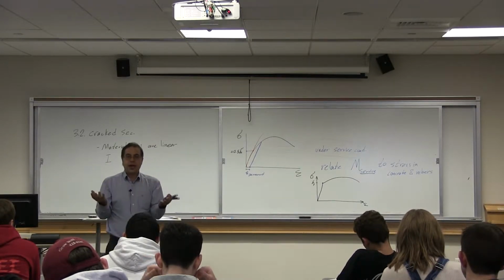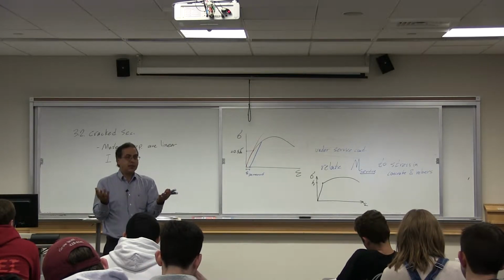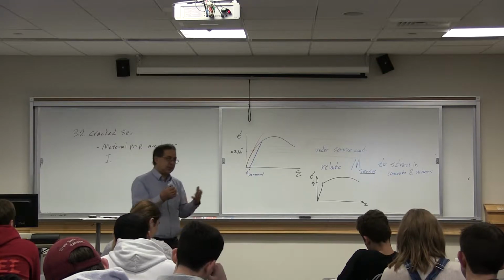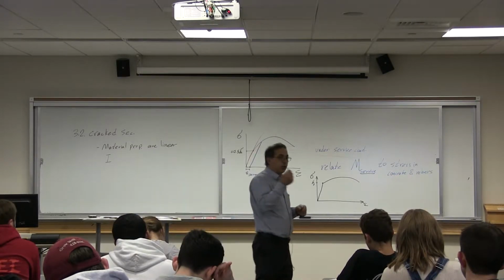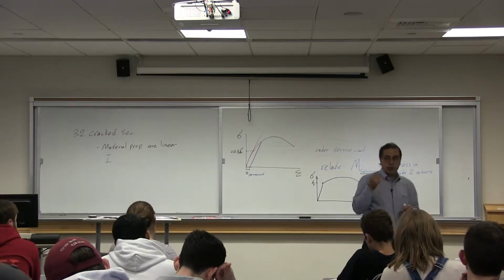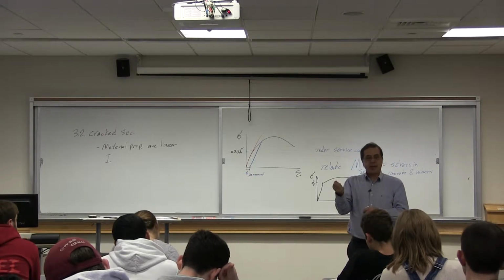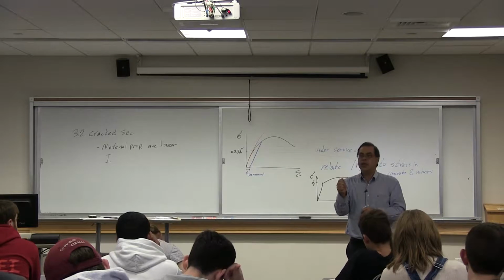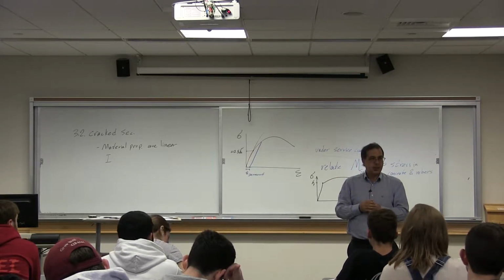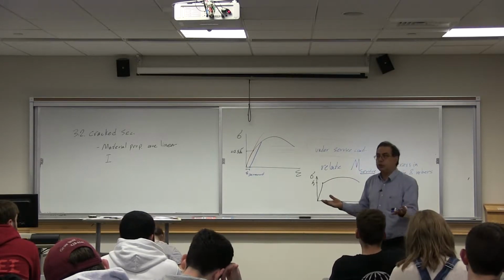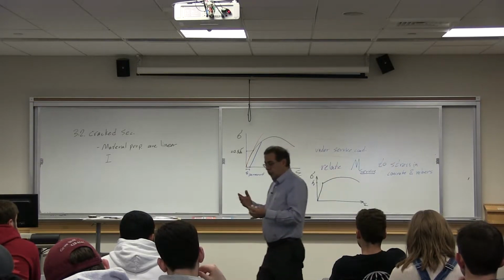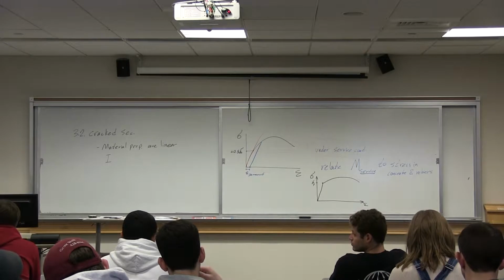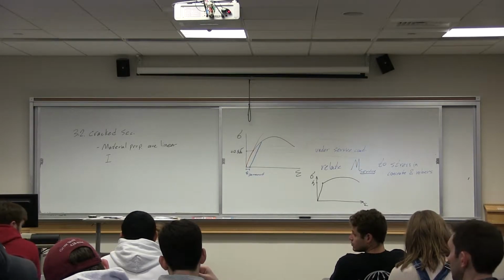So what's a good crack? A good crack is the one that cannot be seen. Of course, when I say seen with the naked eye, if you look at the reinforced concrete structure closely, pick a magnifying glass and know where it would crack, you will see the cracks. But that's not what people usually do. So from a usage point of view, a good crack is the one that cannot be seen.